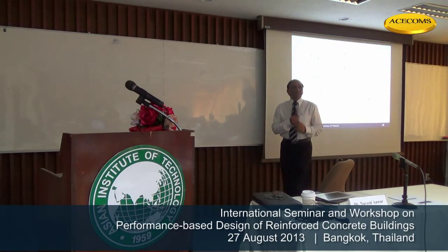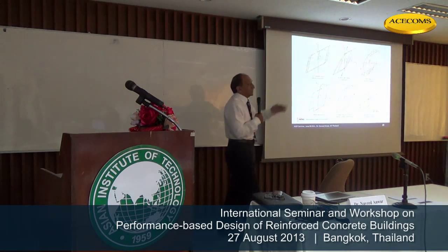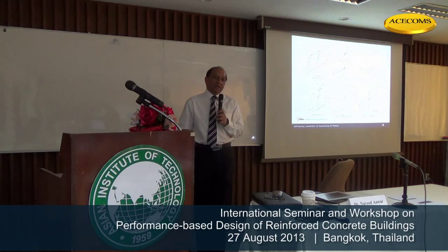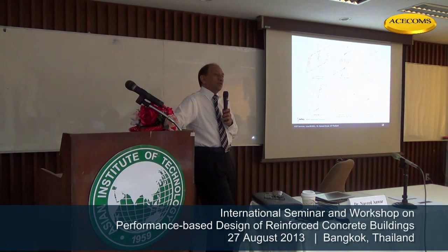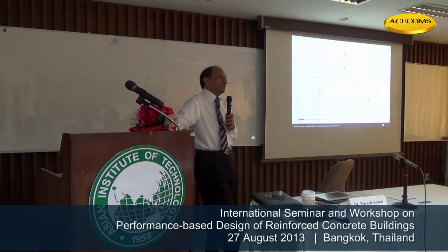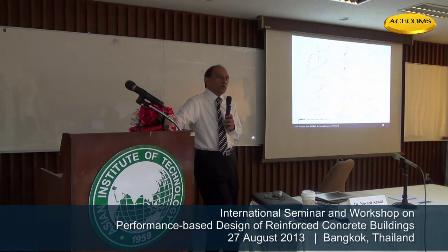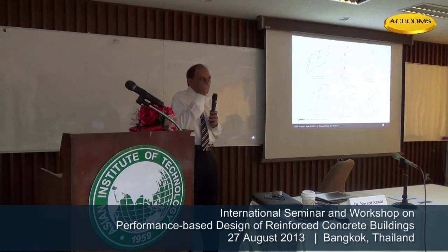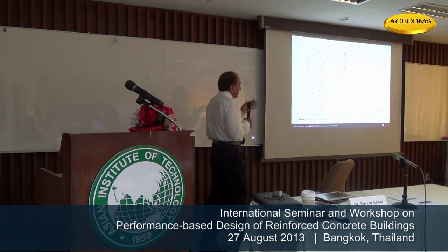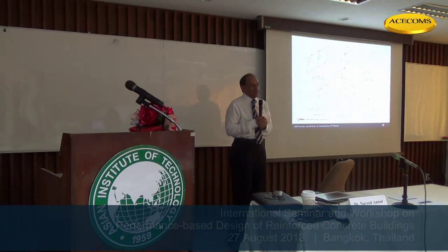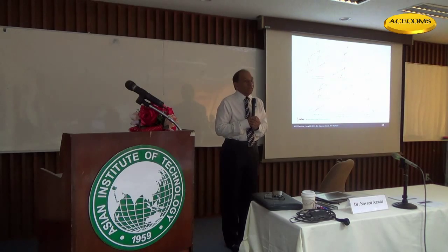They have identified many, but these 6 are primary types of cyclic response that you can expect from a structure during an earthquake. So actual material and actual member may have one of them or 2 of them. Which means that choosing the right degradation or cyclic model is very important in terms of the analysis.